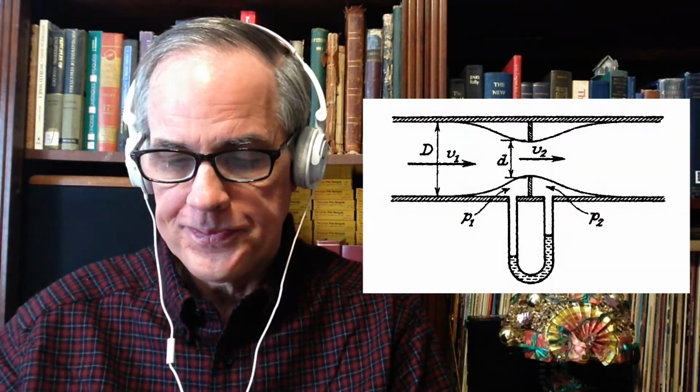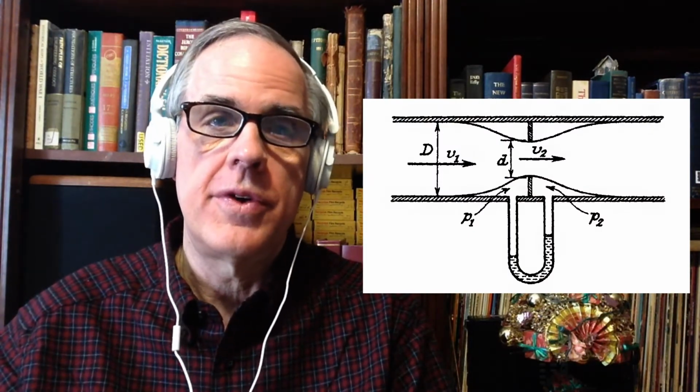And it's still a useful exercise because it shows us how we can actually use these devices in this way, and at the same time take into consideration whatever viscous losses are in the device. Now you say, well, that's all wonderful, but how do we implement that? Well, what we do is we have what are called classical flow meters. The first one is the simplest, which is a sharp edge orifice. We have 2 of those in our setup.